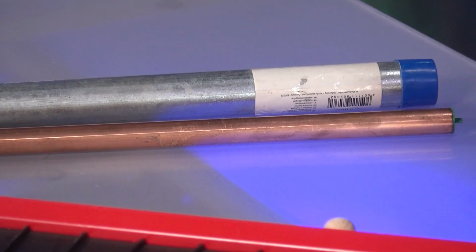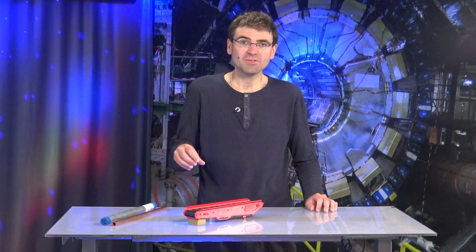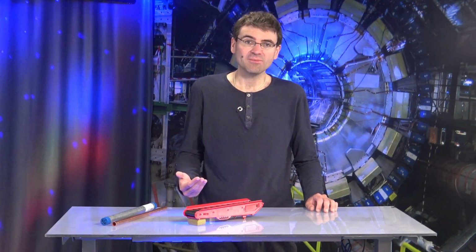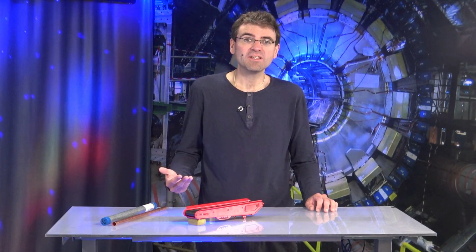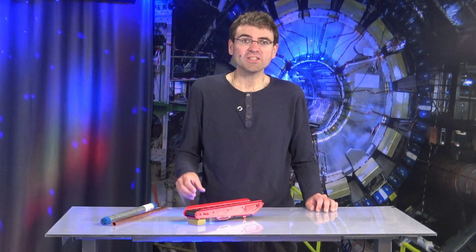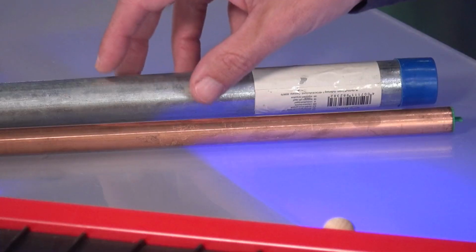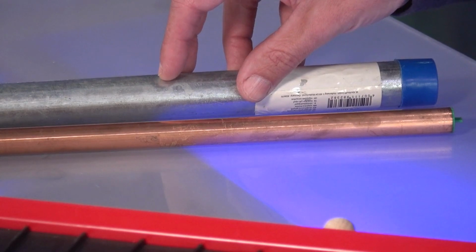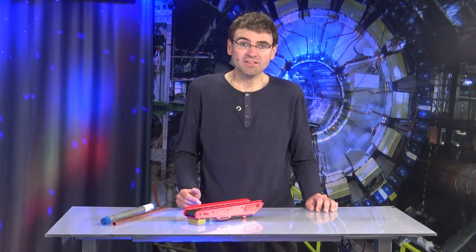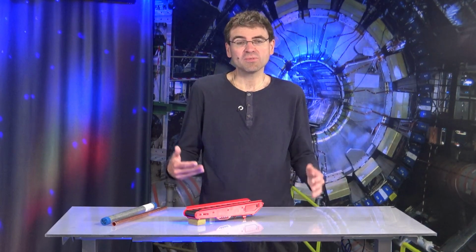In the past, these parameters were measured in the pipes themselves, using an impeller that was driven by the liquid. However, the disadvantage of this method was that mechanical measurements led to wear and tear, and the impeller had to be replaced relatively frequently. So there was an interest in finding out how to look inside these pipes without having to open them. And one of the methods used for this purpose was the transit time difference method.